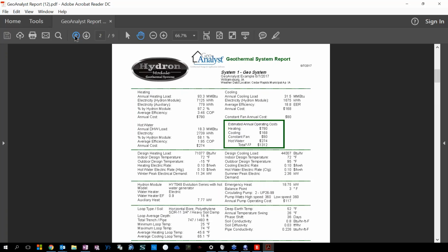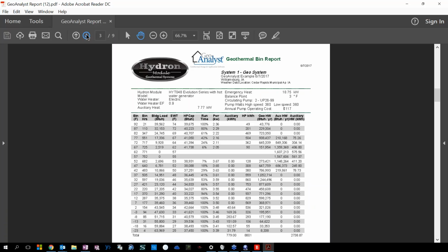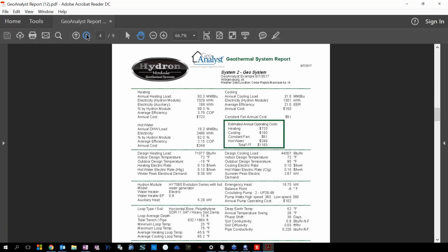So we can't install a 4-ton on something with a 70 or 72,000 BTUs because they go by capacity, not by the annual heating, like I see what you've highlighted there. Yes, sir. We actually have to show that capacity meets 85%. So we have to put in quite a bit bigger system.